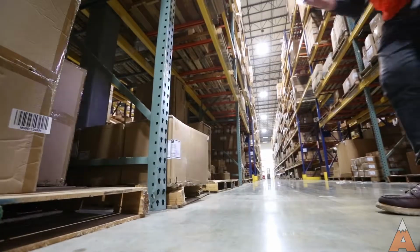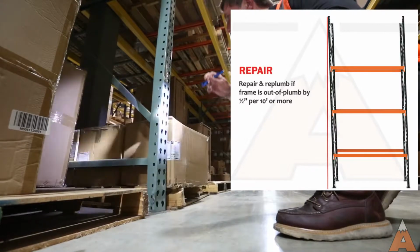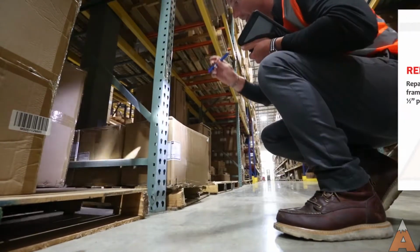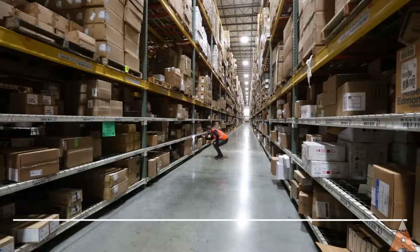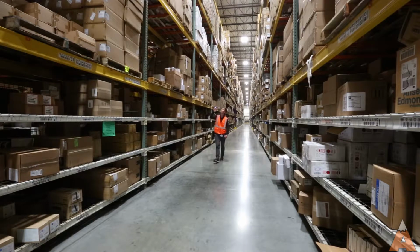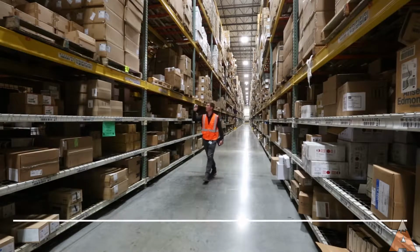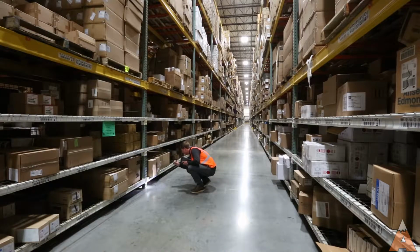If the frame is too far out of plumb by more than ½ inch per 10 feet of height, it needs to be unloaded and replumbed. This is the case for both front to back and side to side. Note: although most impacts occur on the front post, it is important to inspect the entire upright for damage and to also look for consistent damage, which can prove to be more serious.